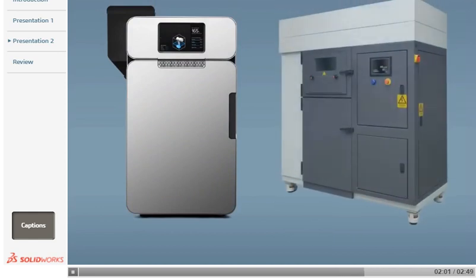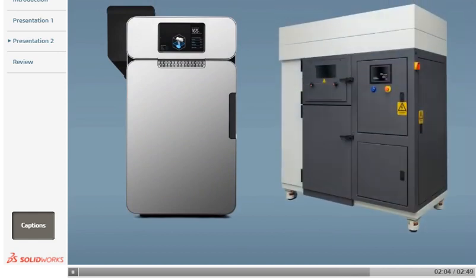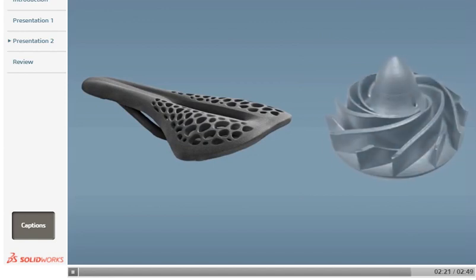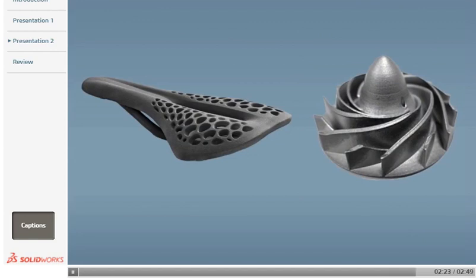The other printing methods, such as SLS and SLM, typically are housed in much larger printers because the processes are more complex and require more parts. One advantage of using these larger, more sophisticated machines is that you can print some of the highest quality parts, eliminating the need for other manufacturing methods. They also can handle materials other than plastic, such as an SLM printer creating metal parts. These machines come at a much higher price point, and are typically used by companies that offer 3D printing services.